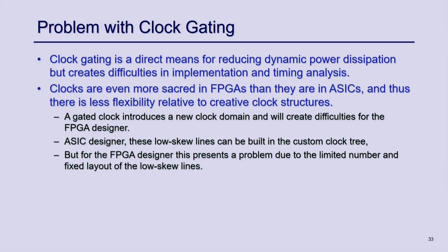Now, I will come back again to clock gating. We have talked about how clock gating is a very useful approach to reduce the power of your design, but the problem with clock gating is that it creates a different clock domain, as I discussed earlier also, and that is actually a problem for the timing analysis tool and implementation.